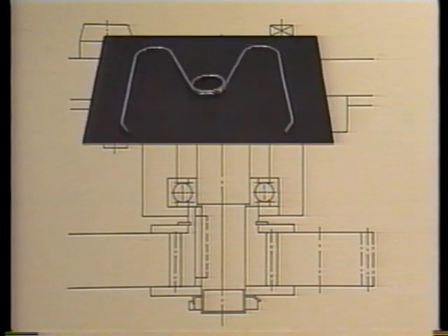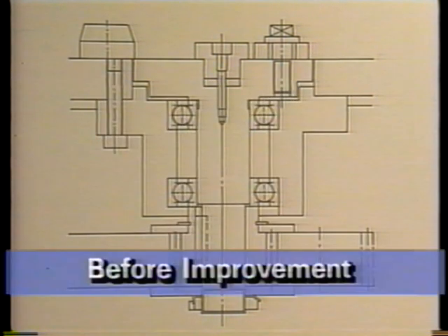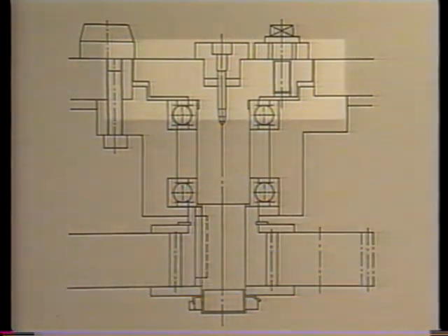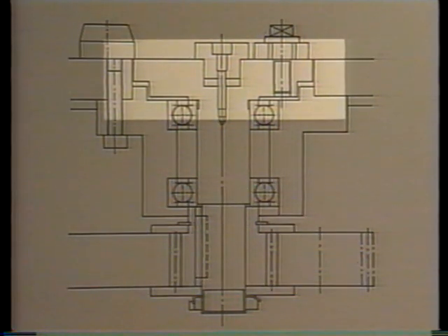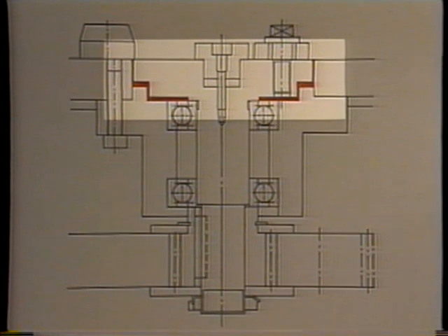This is a diagram of a machine which shapes wire rods, such as this. The rack connected to the air cylinder turns the shaft, and rollers attached to the top of the shaft bend and shape the wire rods. In this example, if the operator is lazy about cleaning, iron dust from the surface of the rods gets pressed between the rollers and the rod being shaped, and can cause scratches as well as getting into the bearings of the shaft, where it can cause damage to the bearings.